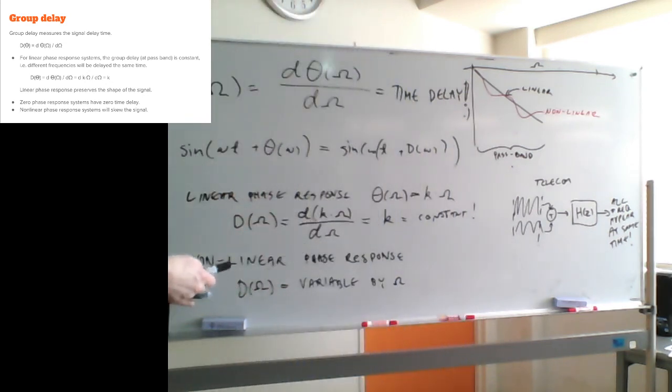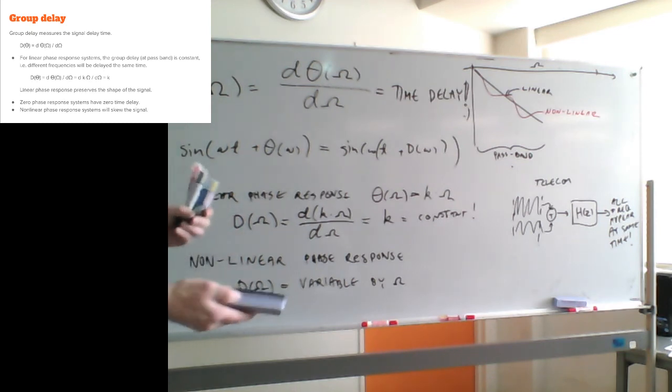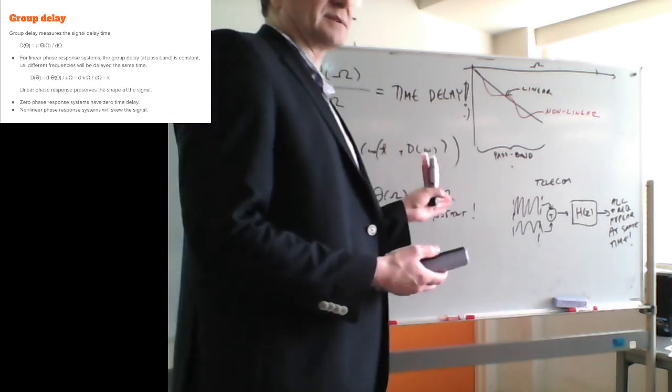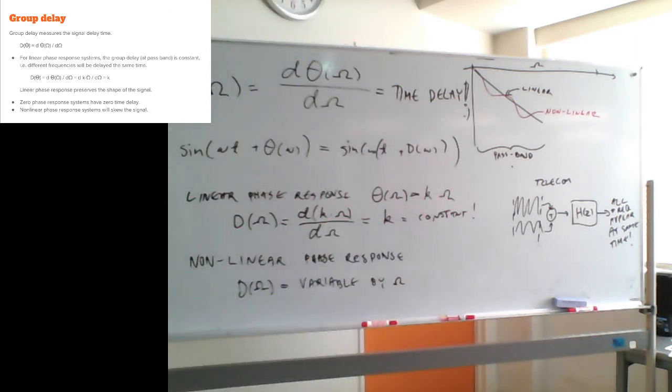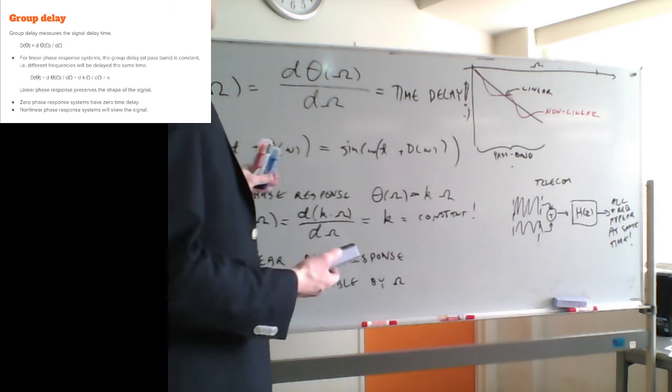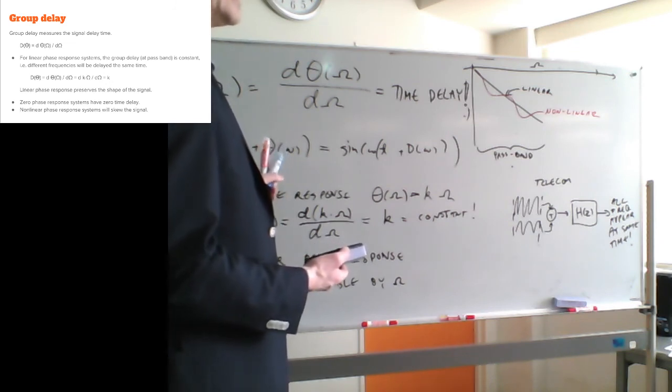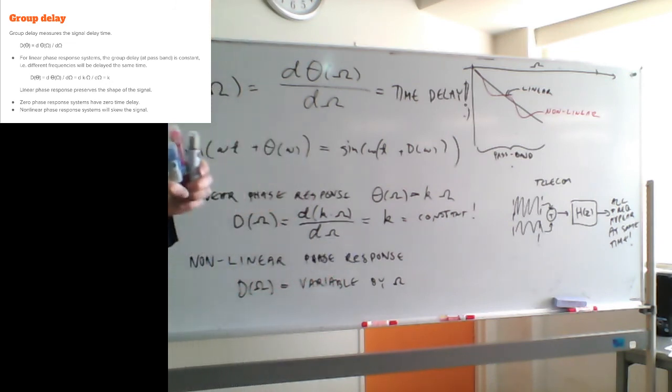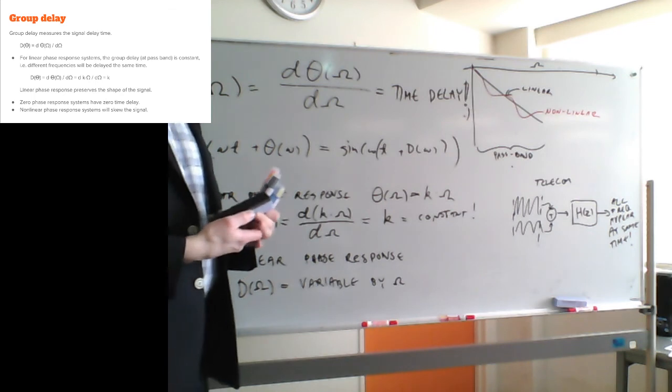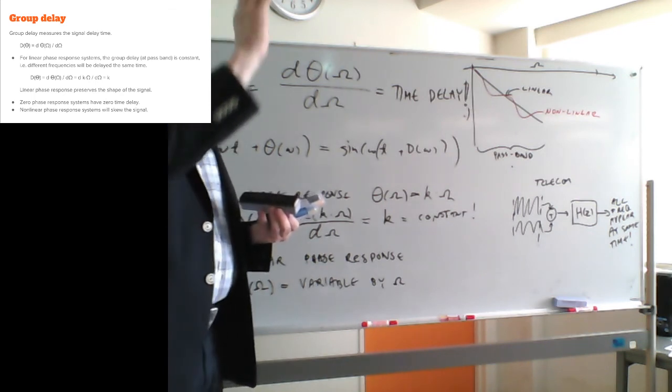Although with a nonlinear phase response, if you can basically tolerate that one, then you can get, say, more effective filters. With the linear phase response filters, you are actually tied into finite impulse response systems. But with the infinite impulse response systems, you can actually have, say, high Q filters easily.